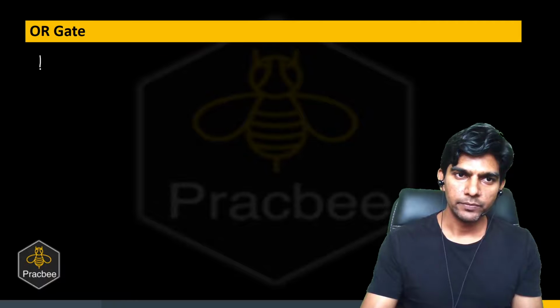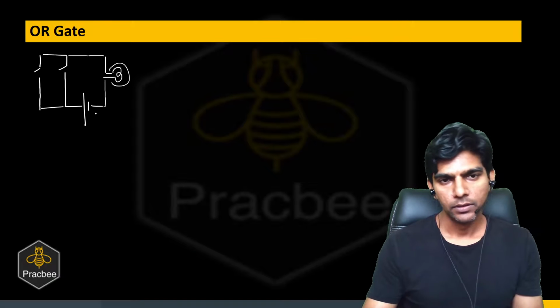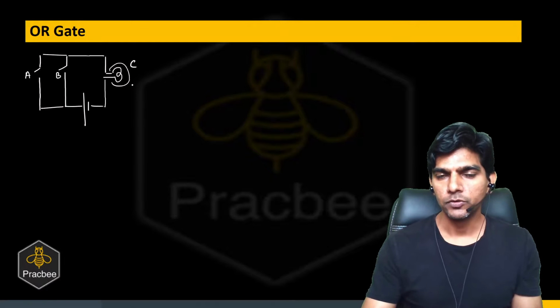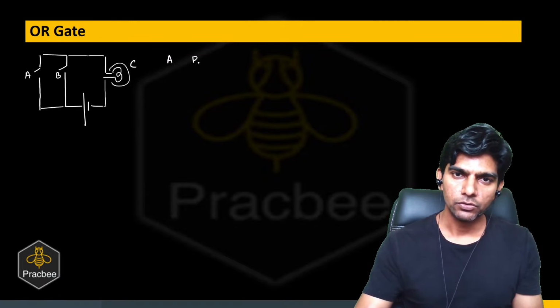Let me first draw the circuit diagram. We have two switches which are connected in parallel, and there is a battery and a bulb like this. This switch is A, this is B, and the output of the bulb is C. If the bulb glows, we have a high output. If the bulb does not glow, we have a low output. So first let us draw the truth table.